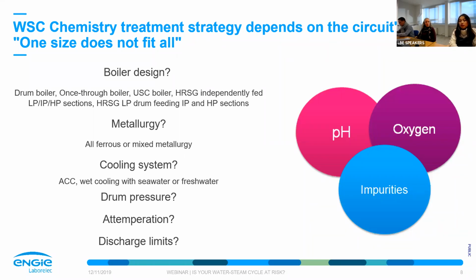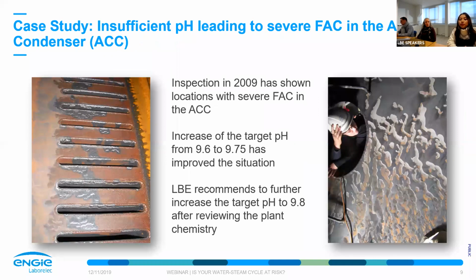And that is really important to answer a series of questions to determine the best strategy. What is my boiler design? What is the metallurgy in it? What is the cooling system, the drum pressure, temperature, attenuation, discharge limits? I will end this question with a case study.